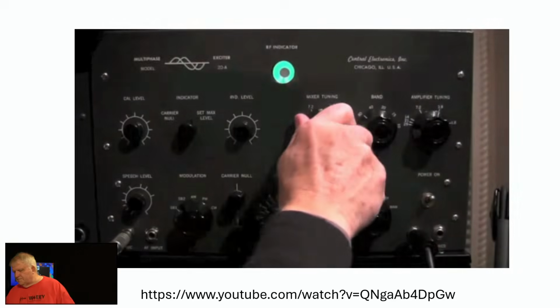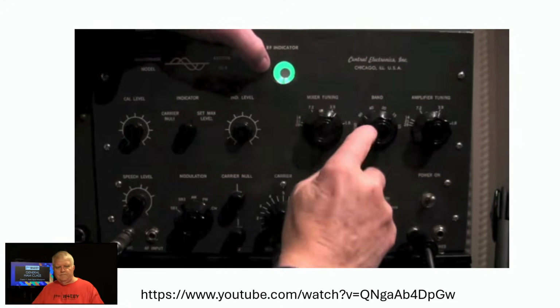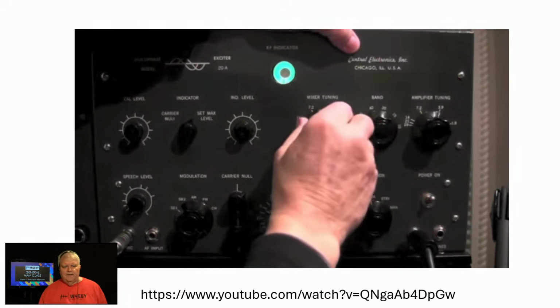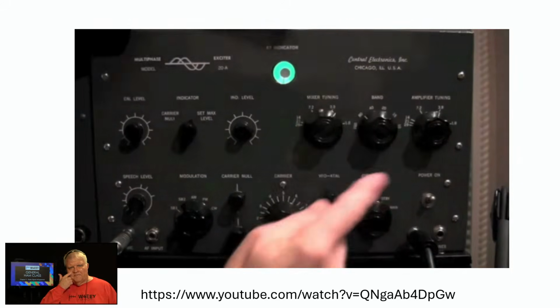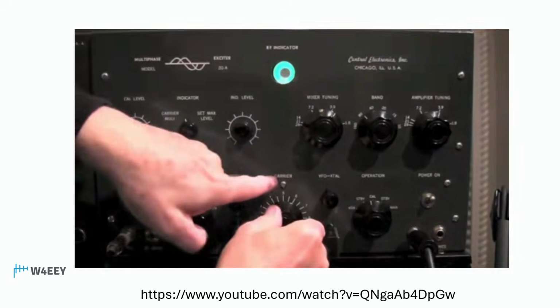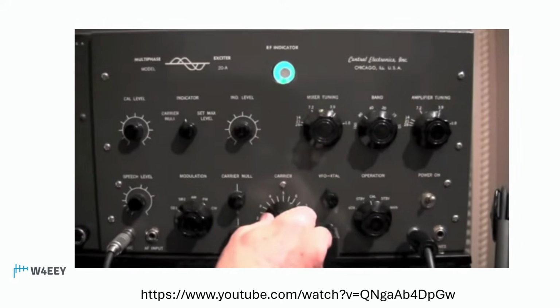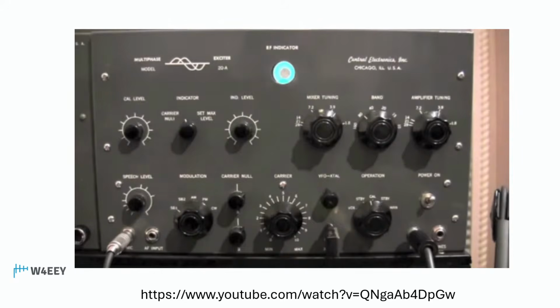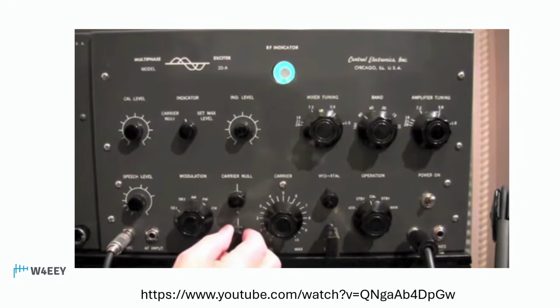This is the Central Electronics, and this is how I tuned it up. You'll hear the receiver. We select the band, 80 meters, 75 meters. Then we're going to put this in the carrier null. Now watch. We're going to take those two out of phase, and away went the carrier. There's our carrier null.